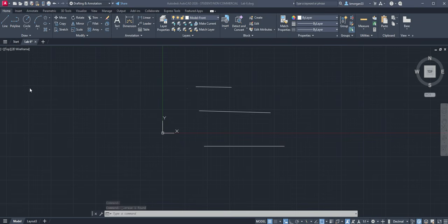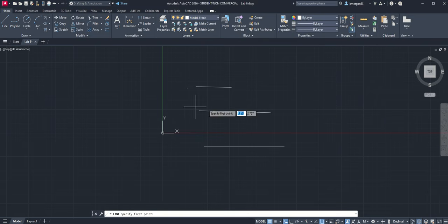Right, the next one is we're going to learn how to turn. So we will go back into the line mode and click on the canvas. Now we will put an angle. The angle is a less-than sign and then 45, which means I am turning 45. Now we have to define how far you want to go. You want to go 3 units, so type in 3 and then enter, and it will give you a 3-unit line.